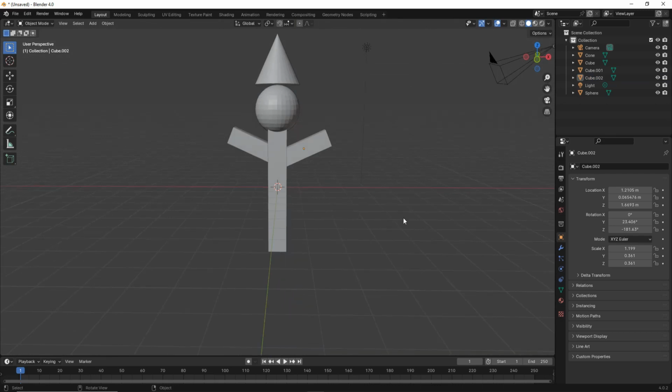That concludes this video. We learned about Blender, its applications, its basic user interface, some of the navigation tools for the scenes, and also how to manipulate the objects on the basic level with moving, rotation, and scaling. We created this figure now of individual parts. You can see in the scene collection there's a whole bunch of cubes there.